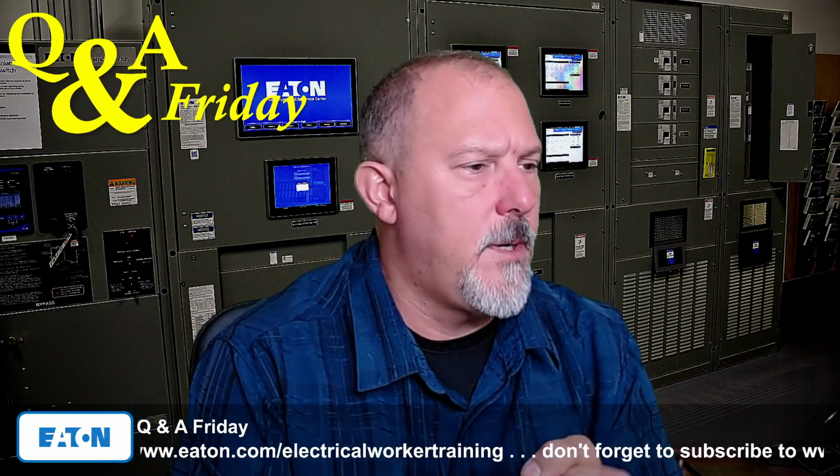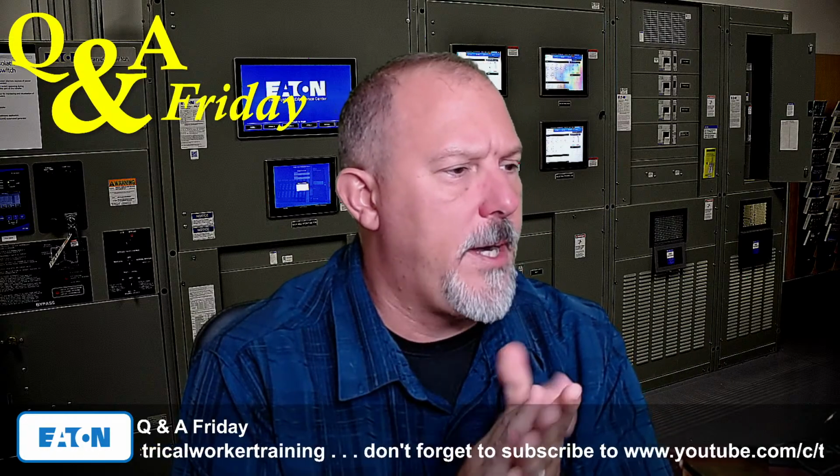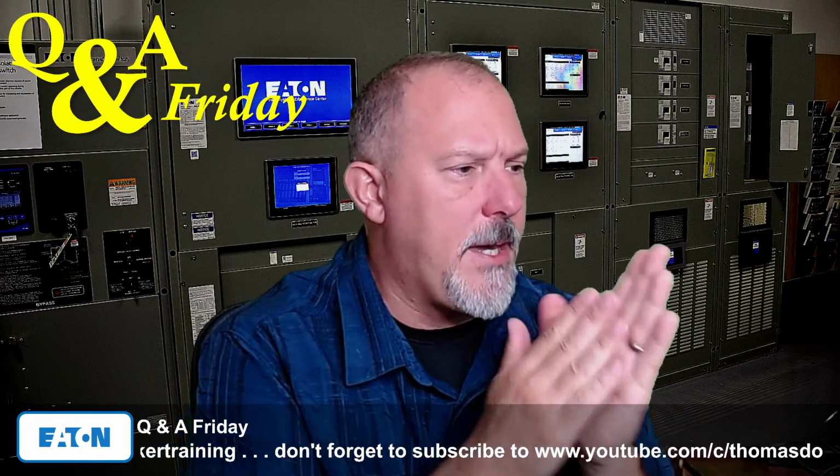Okay, pad mount transformers connected to a multi-megawatt inverter. Often there's need for a small amount of 120 volt power, and this need may be met by mini power centers. This is from JW. The mini power centers normally have interrupting ratings on their main breaker that are too low for the fault current the large transformer may be able to deliver. Sometimes current limiting fuses are needed ahead of the mini power center.